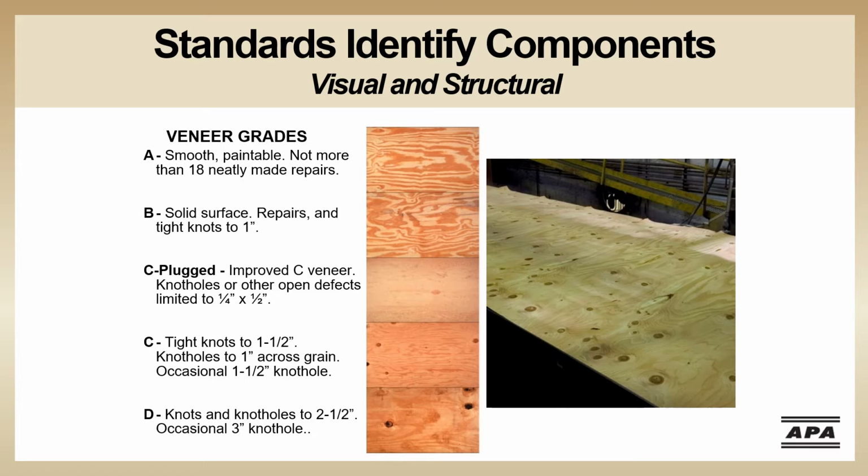There is a C plugged veneer grade that improves a C grade veneer with repairs of knot holes and limitations on other open defects. So A, B, and C plugged faces are nearly solid, and they're sanded if they're A or B, touch sanded if C plugged. C and D faces have greater openings and are not sanded.